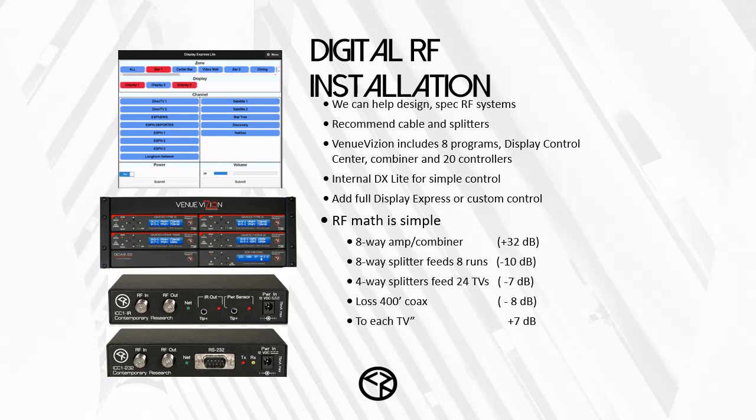Now, if you do have, say, a Crestron or AMX control system you want to use, no problem. Both of those can coexist. So you can go into the Ethernet port, you can go into the 232 port and start writing your code. But as you're writing, you still have the web page to fall back on and to test and see, okay, that didn't work like I expected. Okay, let me do that with the control buttons. Okay, yes, it's working. I missed something in my code. So you can troubleshoot your code as you work.